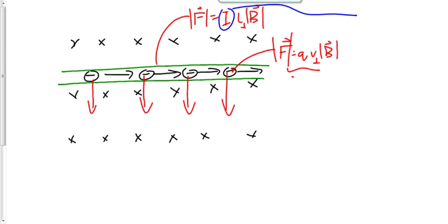And what a lot of people think when they hear that definition, they think the speed, how fast the electric charges are moving. That's not what it is at all. It's not measured in meters per second, it's measured in coulombs per second. So in other words, it's how many charges are flowing per second. Remember the analogy we used the other day? You're standing on the side of the highway with a radar gun, you're measuring the speed of cars. Okay, if you're standing on the highway with a stopwatch and you're counting the number of cars that go by per second, you're measuring the rate of flow of cars.